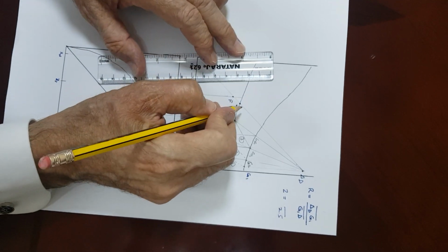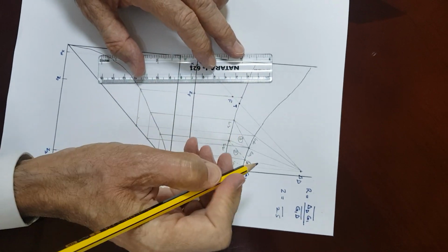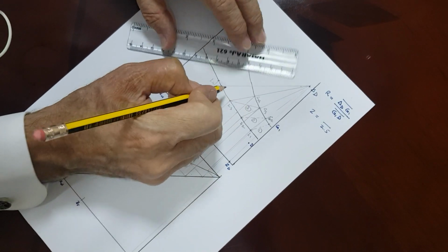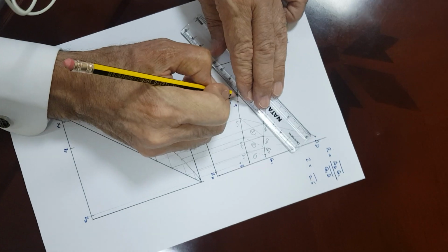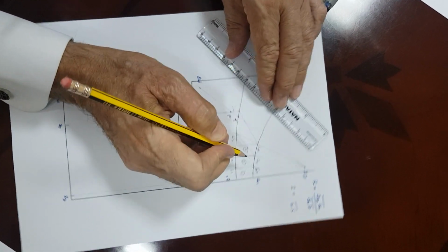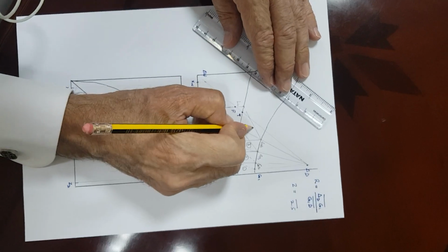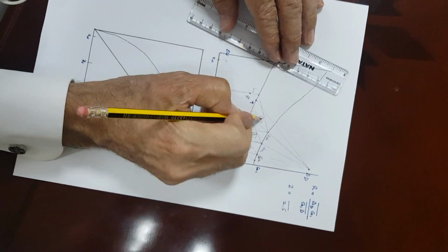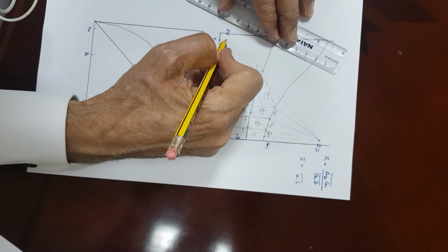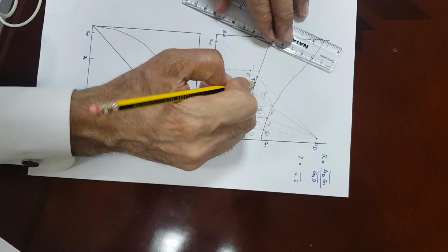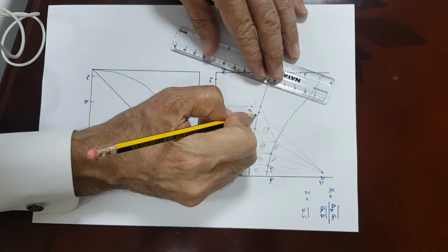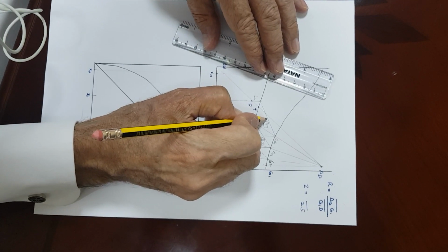Now, as you can see, this is L4. So G4 and L4 are at equilibrium. So this is stage 4. Now this stage is crossing the intersection, or the line joining delta D to delta W, and L4 is past T. So this is actually your feed tray.